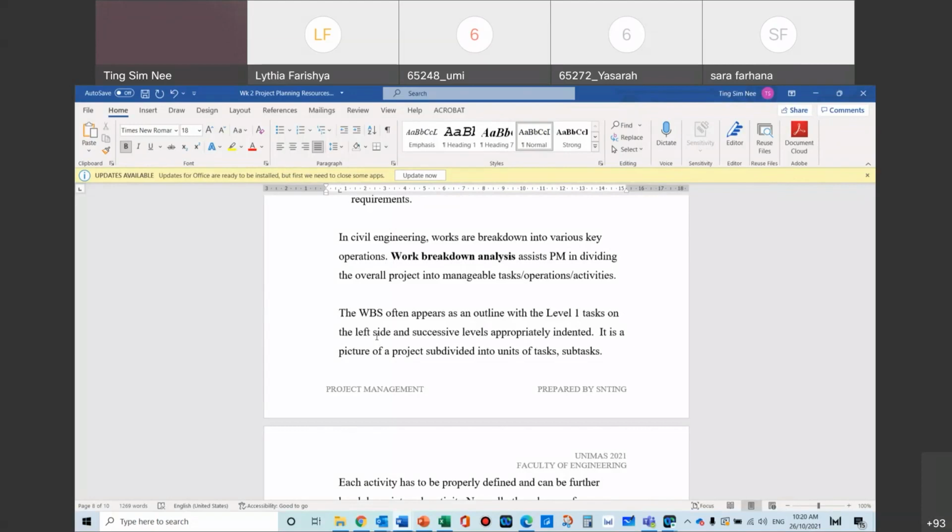So you do have that. And then semi-D, of course, is side by side. So different semi-D will have a different type of work involved as well, because of the architectural design, where we had to pick the architect's design in terms of structures. Then after that, we think about, okay, we will need road work, we will need traffic studies, we will need drainage studies. Before we do drainage work, we need to do drainage studies, the rainfall, the runoff, and all that. And then before you do your pipe design, you need to know the water pressure chart of the nearest tapping point.